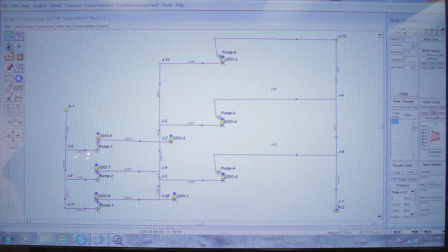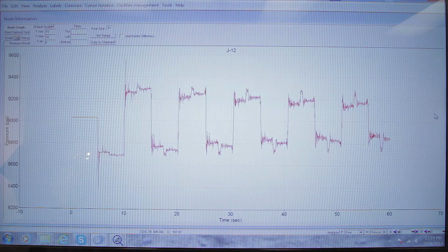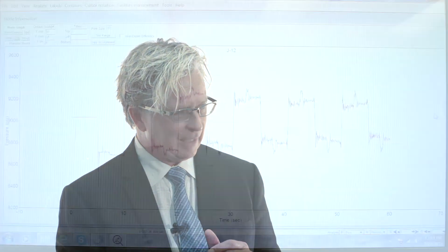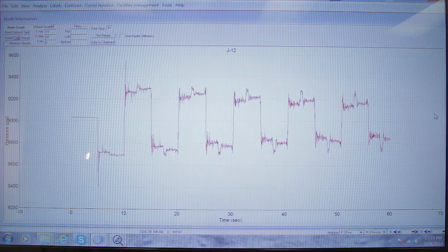and look at what we're looking at from a pressure standpoint. And again, at the injection point, we're looking at a little over 9,000 PSI, okay? And as we're pumping down, when we had a pump trip, we see that pressure dropping down to 8,400 PSI. So it's like an 800 PSI pressure differential within a fraction of a second. And then that wave oscillates down.